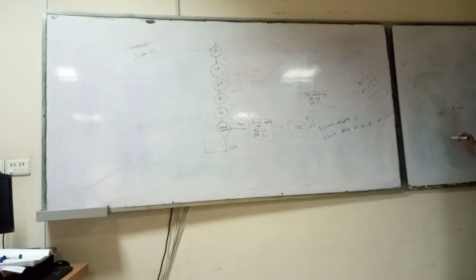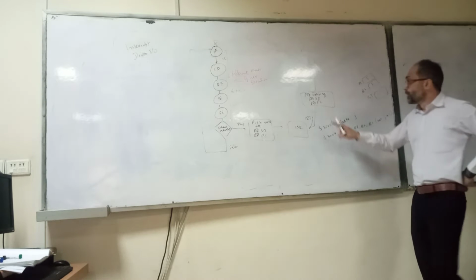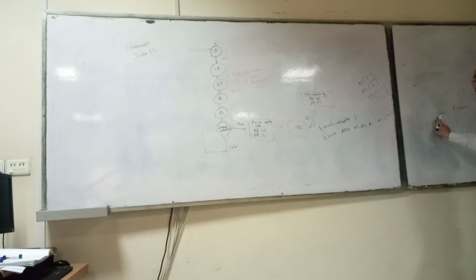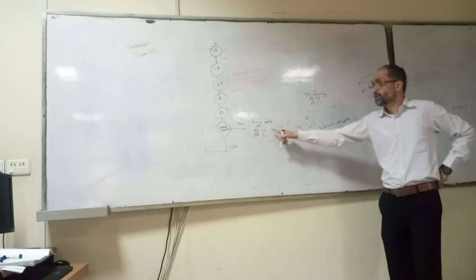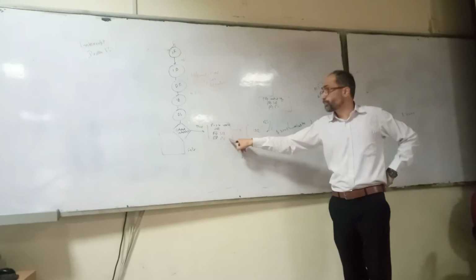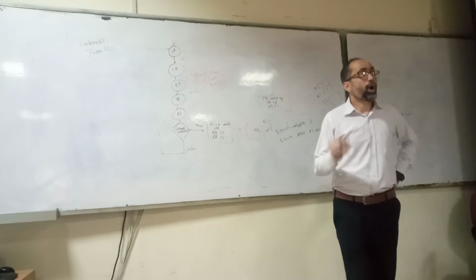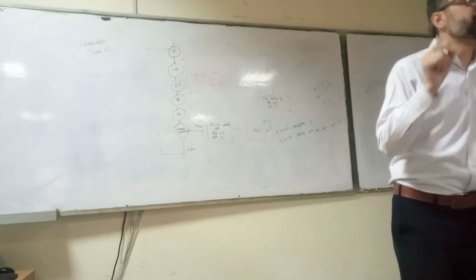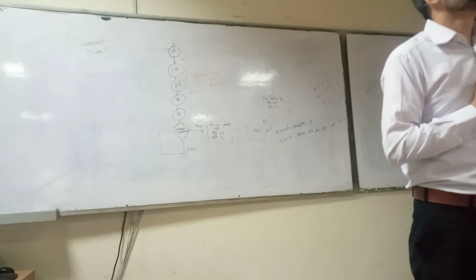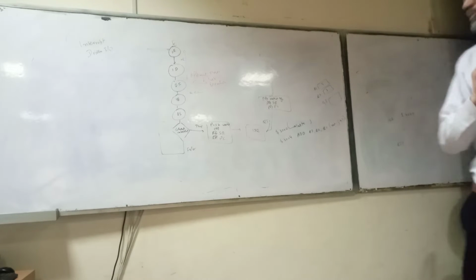The last instruction of the ISR is RTI, return from interrupt. Before jumping to this ISR, what are we pushing on the stack? Status register, program counter and working register. Why do we need to push the working register on the stack? I will explain this in an example.